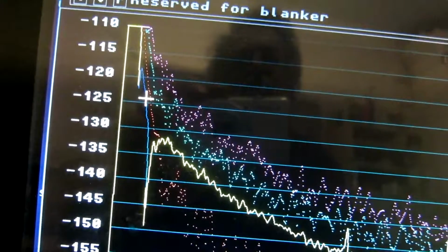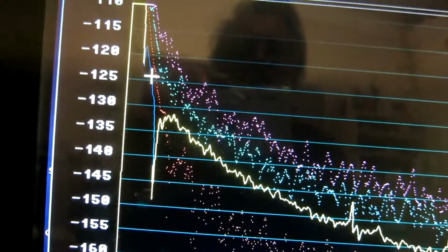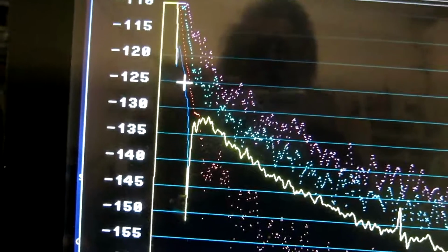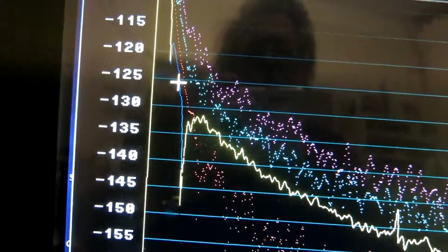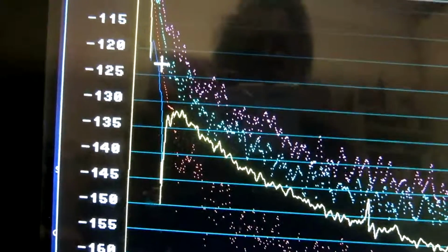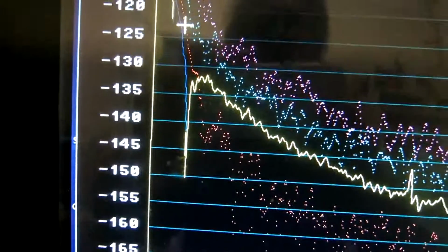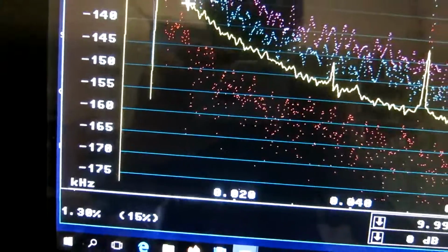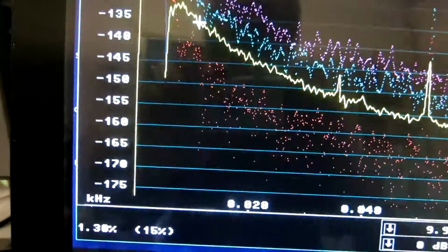This is an artifact of some kind, and it's not the phase locking. It looks like it would be that, but I have verified that the PLL time constant is good enough all the way down to 1 Hz. So I suspect that this is pulling between the oscillators. They go to mixers and there may be some leakage some way, and I will look into that in a separate video. Anyway, down to about here, that is 10 Hertz, the result is probably correct.